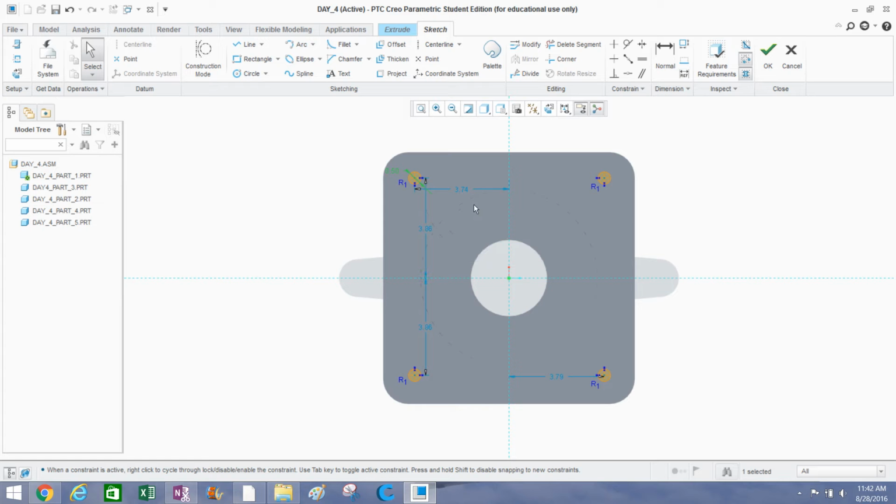Now we'll go ahead and change some of these dimensions. We're going to dimension this 4 inches from the center of the object, since we already have our datums passing through the center, which is really convenient here. So let's go ahead and make everything 4. You'll notice I don't actually need 1 here because I had that vertical tolerance, so it's able to use this 4 and apply it to both holes. Kind of helps a lot when you're doing parts, and it makes sure that everything lines up and moves together if you were to change that dimension.